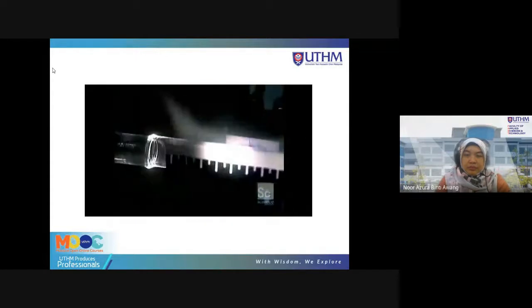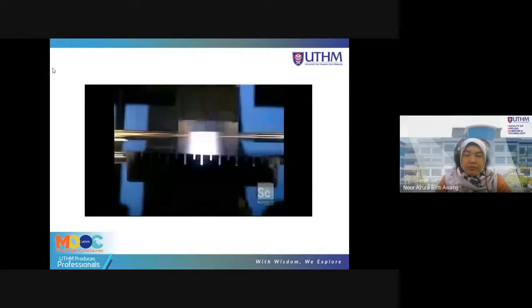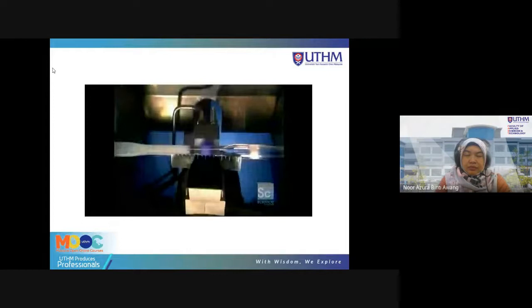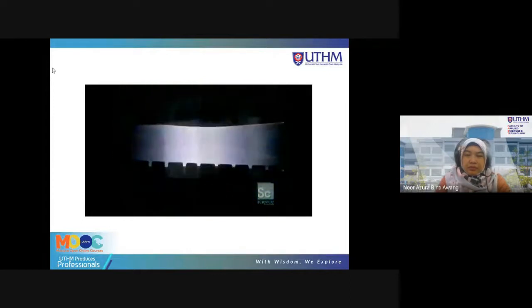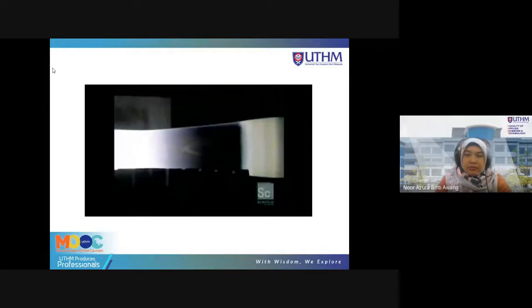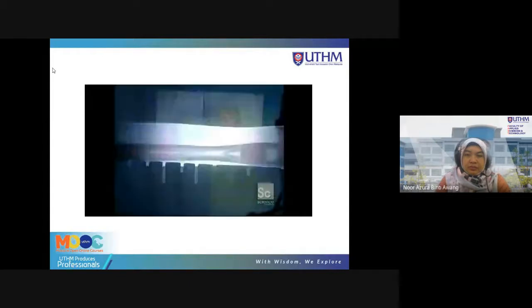Forming what will eventually become the core of the optical fiber. The glass tube itself will form the fiber's covering. When there's enough fused soot, they turn up the heat until the soot itself turns into glass. Then they heat the glass tube enough to soften it and the new glass inside. The intense heat eventually makes the tube collapse on itself to form a solid rod.